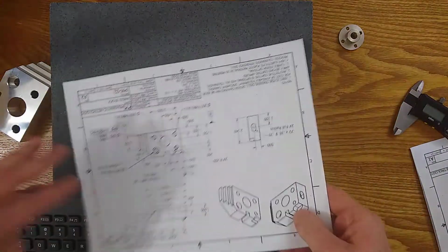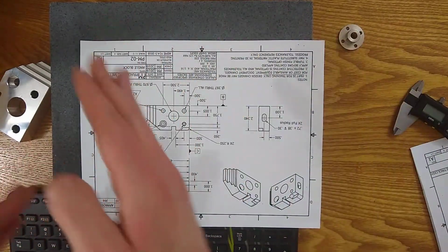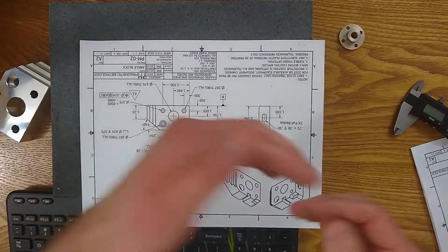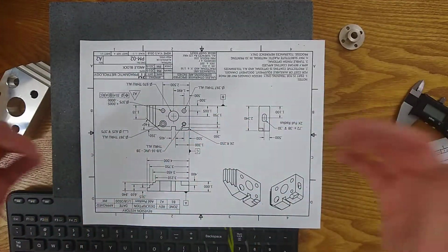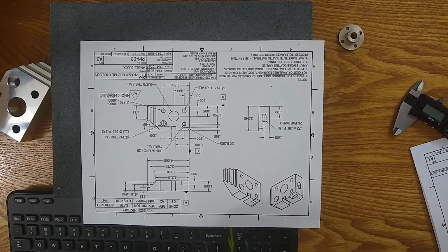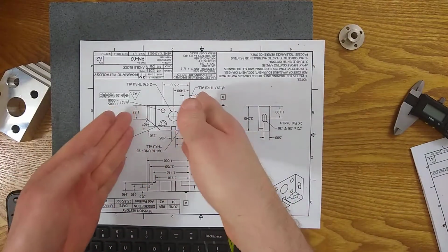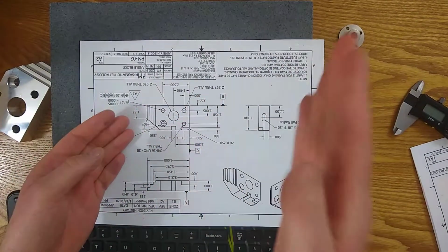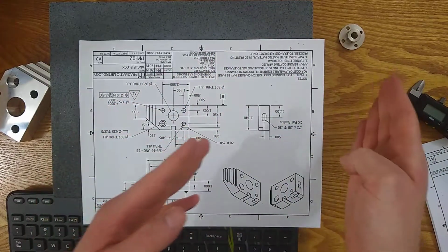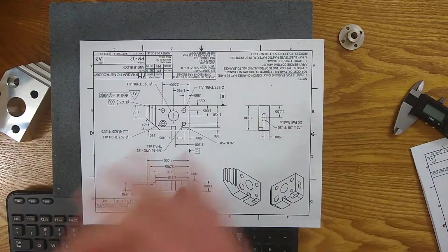You may have features coming from the right side, features coming from the left side, and both of them are horizontal requirements. So sometimes you're going to have to go with those implied datums just based on where the leaders are attached, which surfaces they're attached to, and what center points or depths they reach.